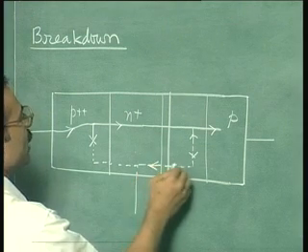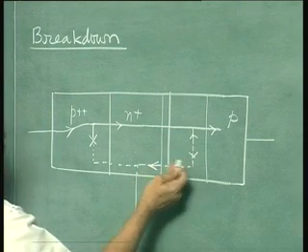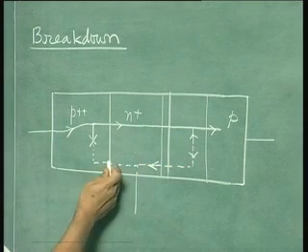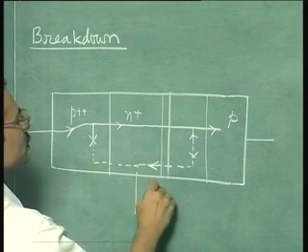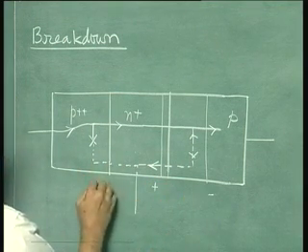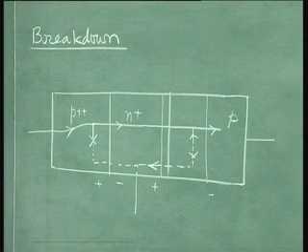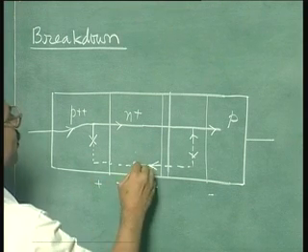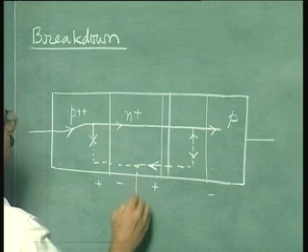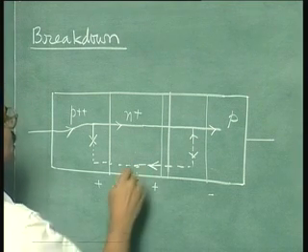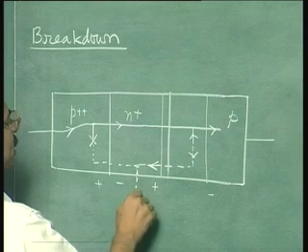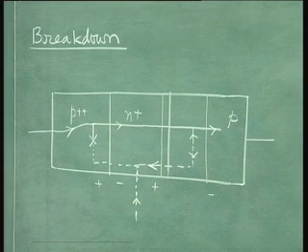So this electron current, these electrons move from collector to base, whereas here the electrons are moving from base to emitter. This is reverse biased, whereas this junction is forward biased. And all these electrons, the base supplies the electrons. This is the picture below breakdown.